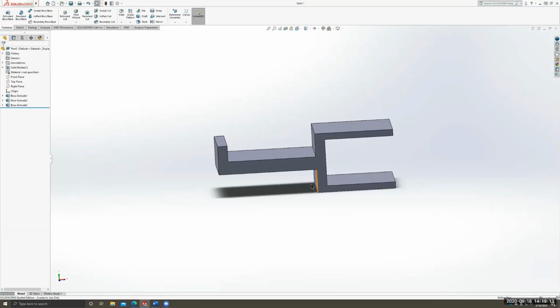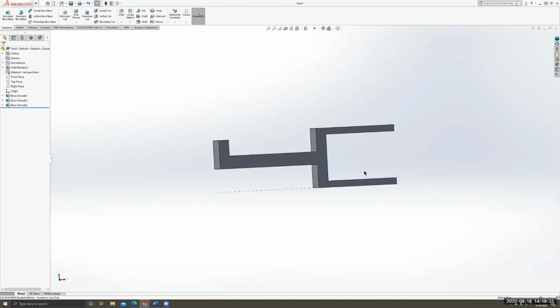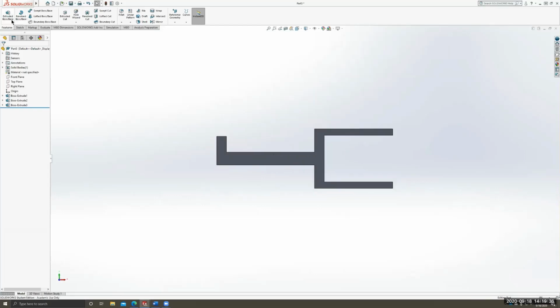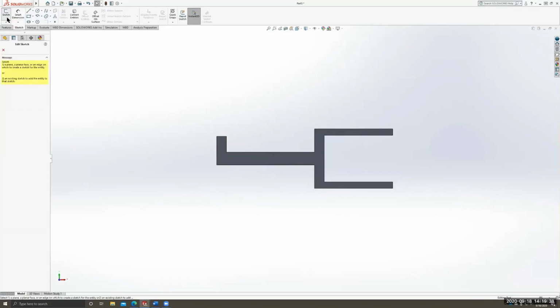Also, I noticed in my very first version, I left it like this, and it would sometimes fall off the desk, mostly because this was too thick. And then sometimes this tongue, this arm, would bend a little bit. So in my second version, I added a little support, that little triangle there. So we're going to add a support because we don't want our headphones falling, because headphones can be expensive.